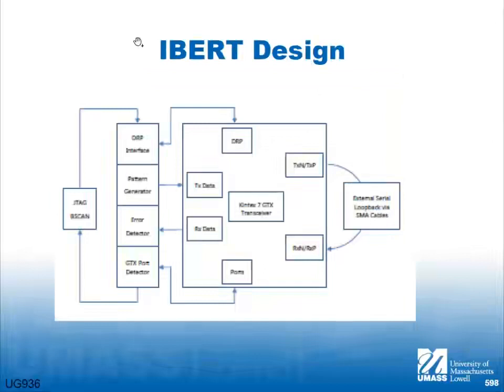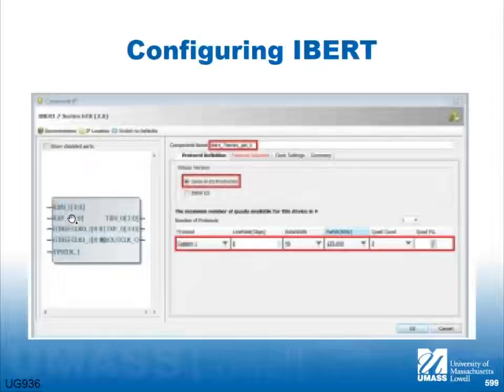Okay. I just put these couple of slides in for information. There are bit error rate testers in FPGAs as well. This is embedded test equipment in the FPGA that does bit error testing, and they specifically do it for those high-speed interfaces that are available on FPGAs. Not important for us, but one thing to note is it's also generated and detected by the boundary scan, the JTAG port for boundary scan.